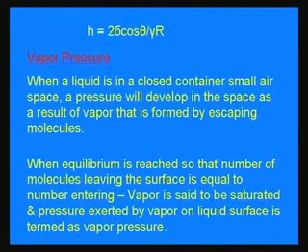So, this capillary rise or fall we can derive as h is equal to 2 sigma cos theta by gamma into r, where gamma is the specific weight and r is the radius of the tube, which we have seen in the previous slide. And then another important property is called vapor pressure.